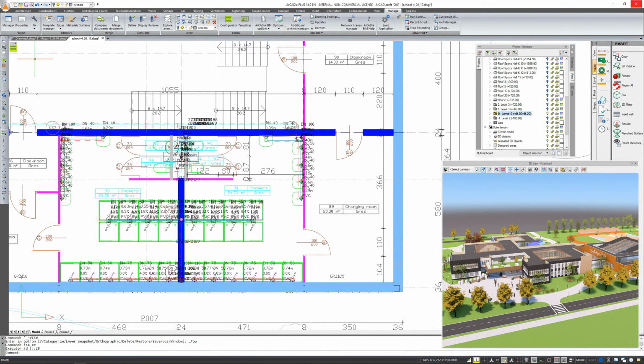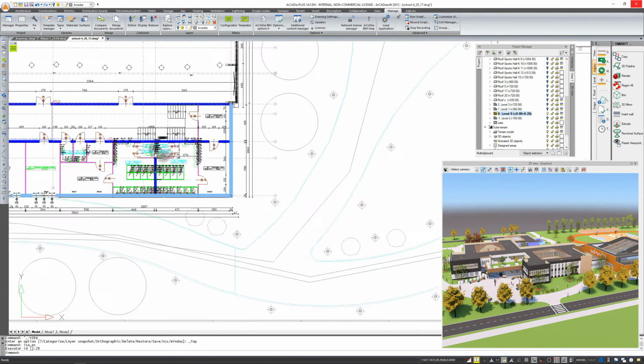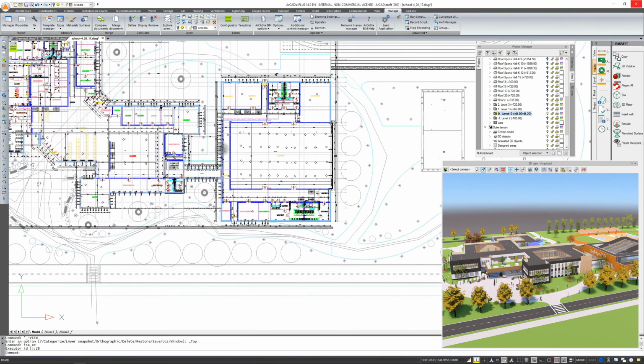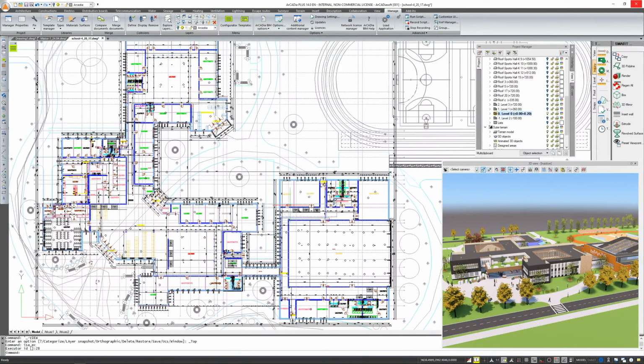These parameters will, of course, be mapped on the view, and possibly the axonometry or the cross-section, if we leave it in. On the other hand, the 3D view will no longer be available, and it will not be possible to insert any other view. The flatten option is on the Manage ribbon, here under the Fix icon, and it does not flatten the document if we have 3D CAD inserted, but it deprives our project of any information about ArCADia.